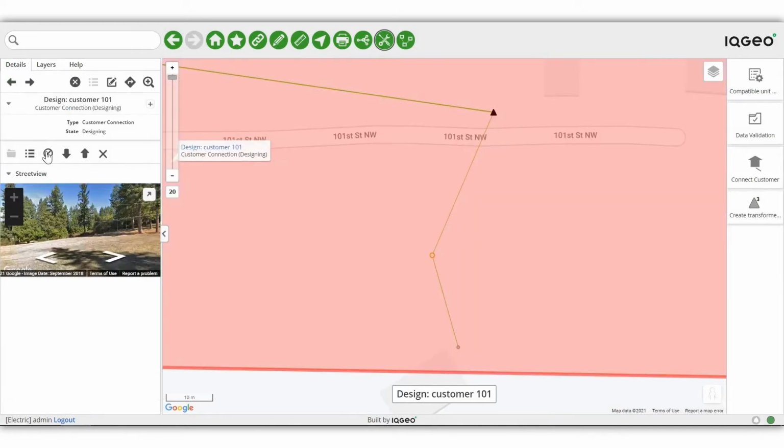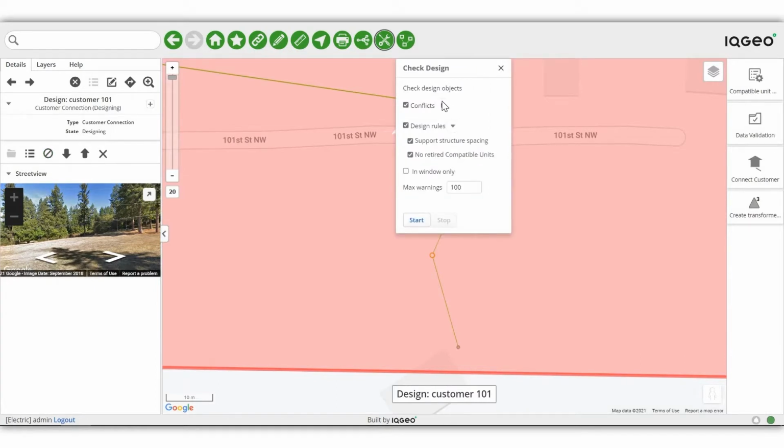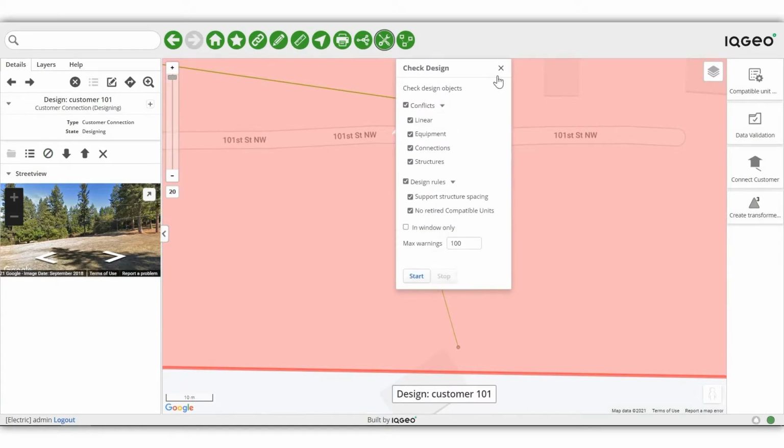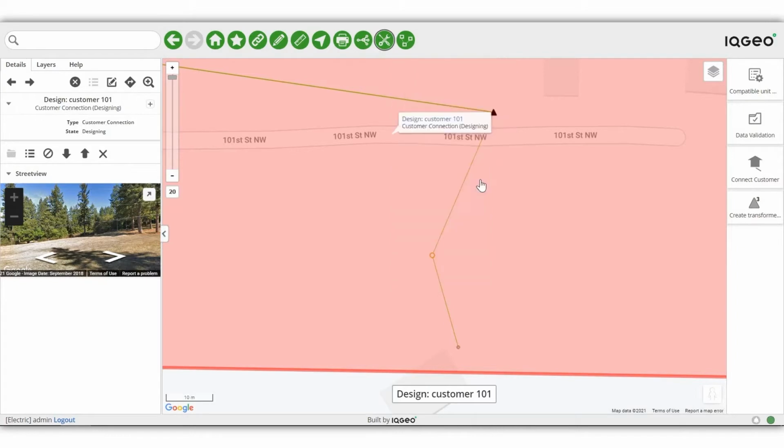The design can now be fed into a validation process, which is based on configurable design rules that align with your internal standards. You can check the design rules before you merge and run the validation. Any conflicts will be highlighted as warnings in the Details panel on the left-hand side, allowing you to resolve these conflicts before posting the final design. If required, you can output your digital designs into a PDF for printing. Freehand text and drag-and-drop objects can be included in the advanced predefined plot template.